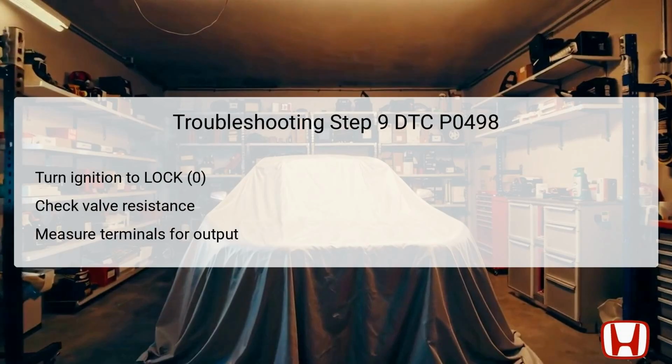At room temperature, the expected resistance should be approximately 25 to 30 ohms, which confirms that the valve is not shorted or open-circuited. Resistance checks are vital in diagnosing whether the component functions correctly. Values outside this range may indicate internal faults within the valve. This final measurement serves as a definitive test in verifying the valve's operation before proceeding to repairs or replacements.